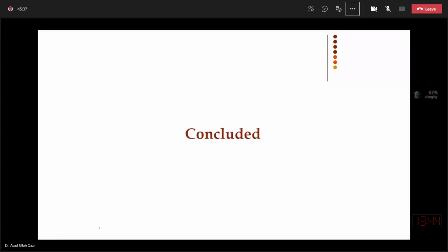So this is the discussion on analysis or design of tension controlled under reinforced beam and analysis of over reinforced beams. In new design, we will not recommend designing an over reinforced beam. But while making analysis, you may come across a beam which is over reinforced and you have to submit its capacity. Then you need to follow this flow chart to determine the capacity of the over reinforced cross section. But in new design, your design will not be approved unless you design the section as tension controlled under reinforced.